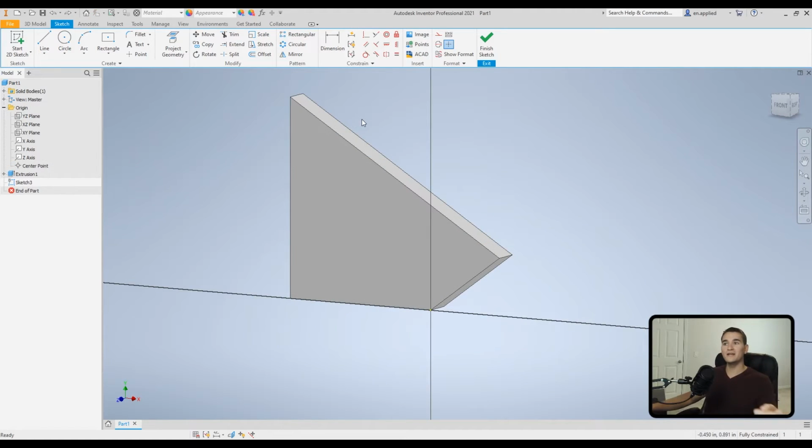Okay, so our next constraint tool is our edit coordinate system. To get here, you just pull this little drop-down menu open, and you can tell there's a drop-down menu there by that little arrow, and you click edit coordinate system. You'll notice I created a 3D body of just some arbitrary shape, because what we can do is edit the native coordinate system found when creating a sketch on a plane. So in this case, I'm creating a sketch on this plane.